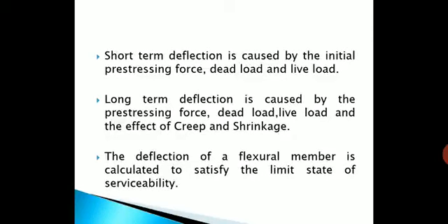The important thing to note here is, while calculating short-term deflection, if losses in pre-stress are given in the problem, the initial pre-stressing force has to be taken, whereas to find long-term deflection, the final pre-stressing force, that is after deducting the losses, which we have already done in a few examples in the last module, has to be taken.